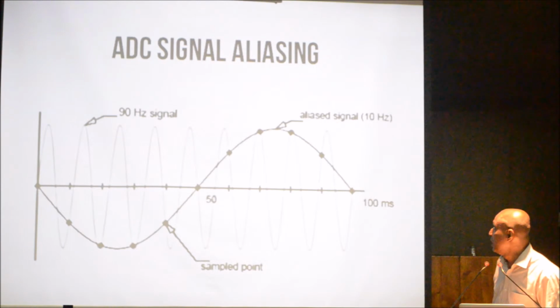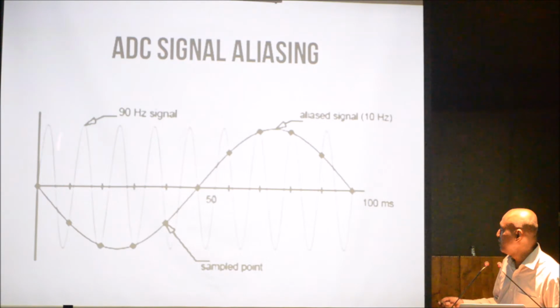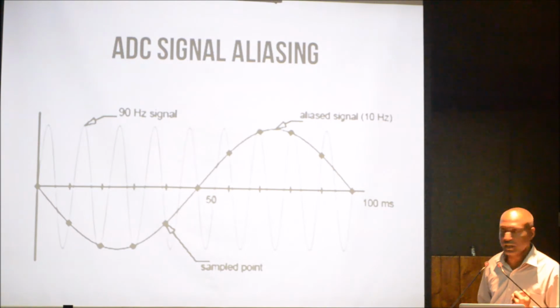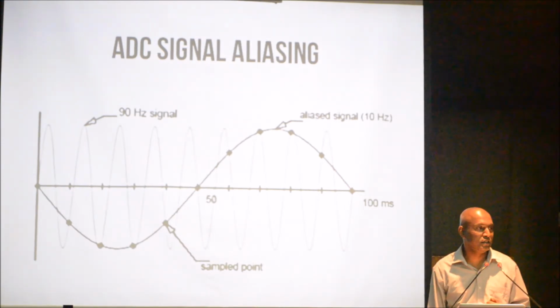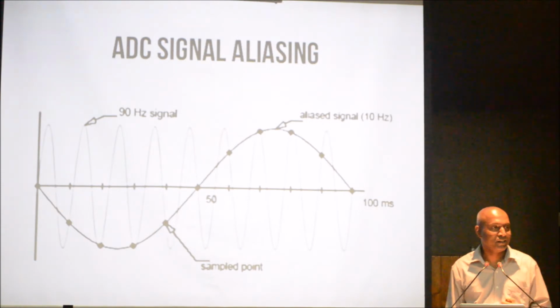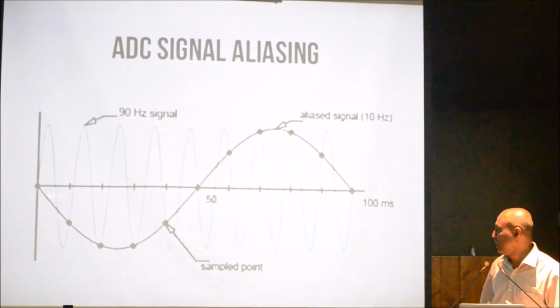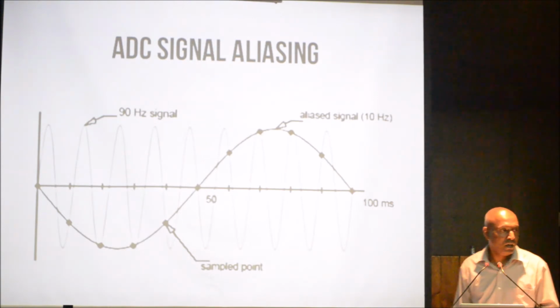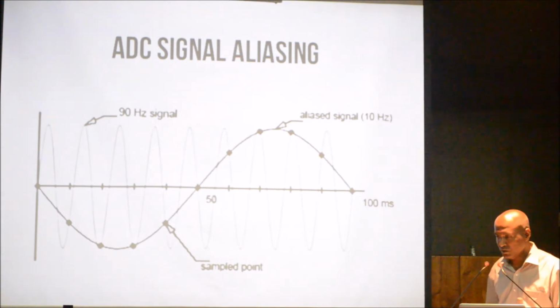The other thing is signal analysis. Now, if you take this example, you see that my physical signal varies like this. But the samples I take out from this physical signal are these points, right? But apparently what I have got is a completely different signal. So this gives a very invalid output for us, which is totally wrong. Now to correct this, our sampling rate should be at least twice the signal frequency. So those are important things that we need to consider.